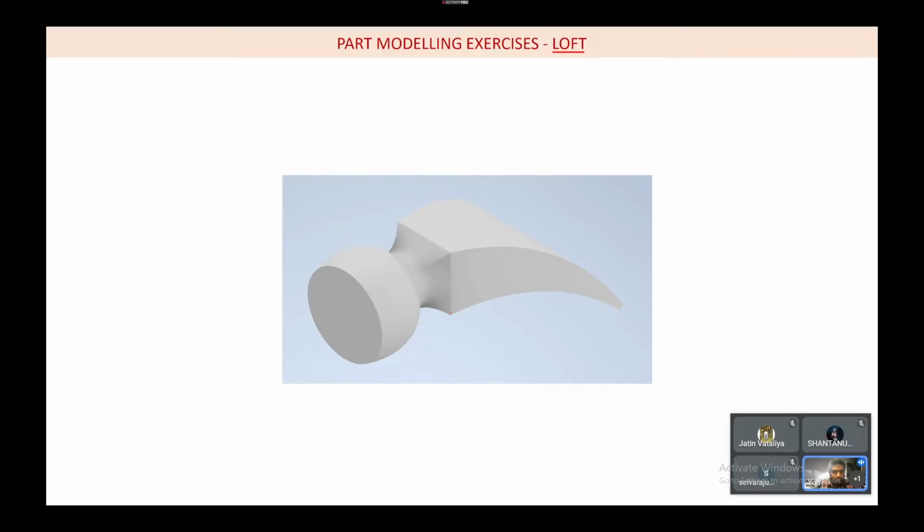Before going, let us say that now I want a circle in such a way that my center should be at this point and my radius should be up to this point. So first what we are going to do, we are going to project this point. Before projecting, I don't want this to be part of the sketch, so I just create what is called construction. Okay, so I select the construction. Now I am going to project geometry and I am going to project this point. Now some yellow color line is created. It is a construction point which has been projected.